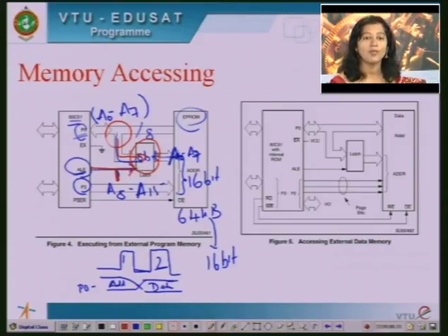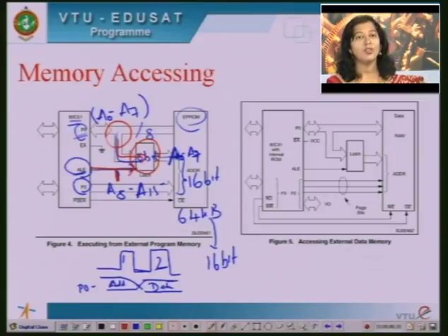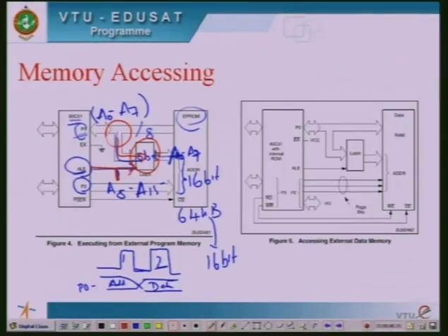So this is how, what are we doing here? Why are we using the same port 0 8 pins to carry address for some time and then data for some time? Remember, we are saving on the area, the number of pins needed, and only the timing will vary. During one clock cycle I send the address, then I save that address on some latches using the ALE pin. The ALE pin is to enable the latch to store the address which is present on port 0. Now, port 0 is free to carry the data in the next clock cycle.